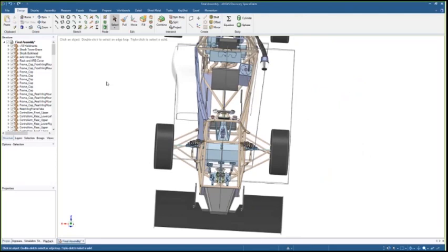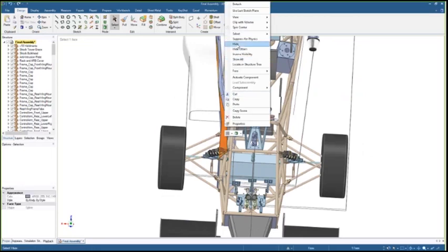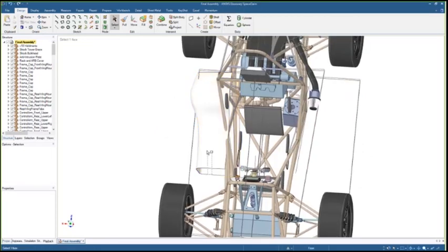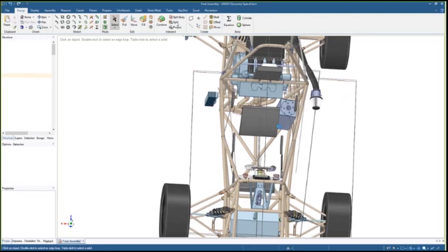Actually, one thing you can do is hide things. So right-click, hide. There's keyboard shortcuts like Control-H. You can box select things and hide, and so we can reduce it down here. I've already done that some. There are a number of parts that we need to hide, so I've hidden them and saved it, and I'm just going to reload that here.